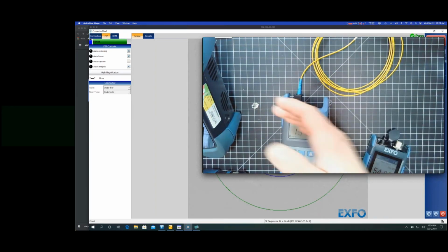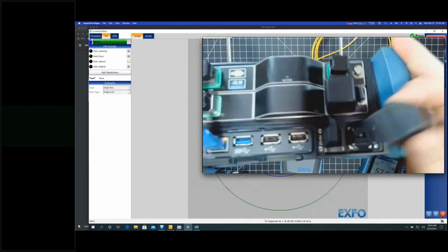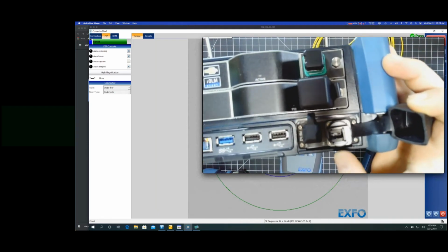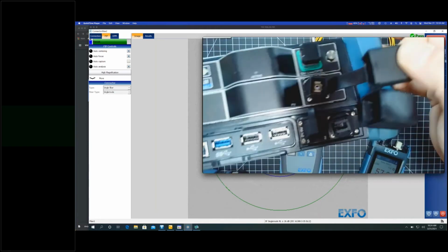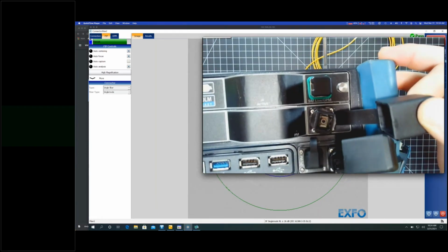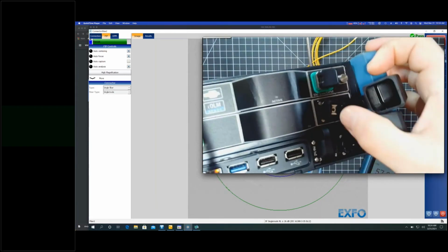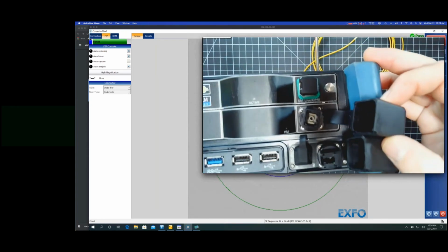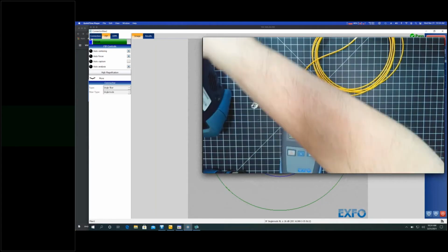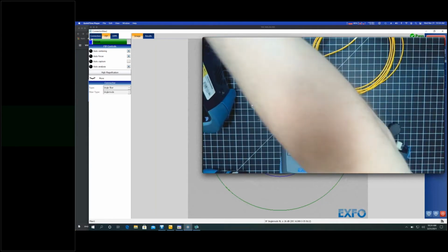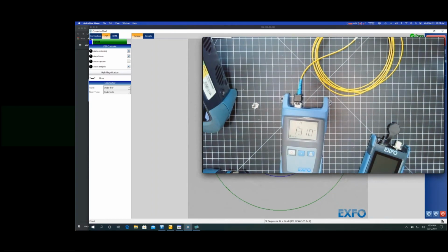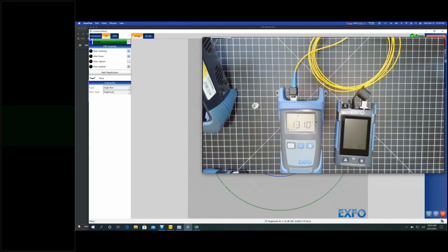It's going to be the same for any of my power meters on my OTDR, FTB, or the power meter on my FTBX 945. All of them have a connector type versus a universal. However, they're not actually connecting to a ferrule. So they're agnostic to whether it's angle polished or single polished, you just need to match up the actual connector type.